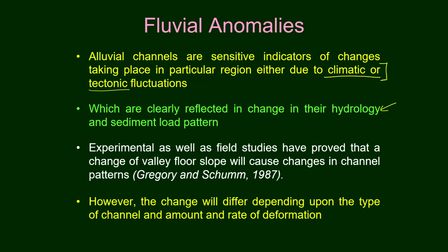Experimental as well as field studies have proved that a change of valley floor slope will cause a change in channel pattern. The valley floor slope we have to consider is your longitudinal profile.